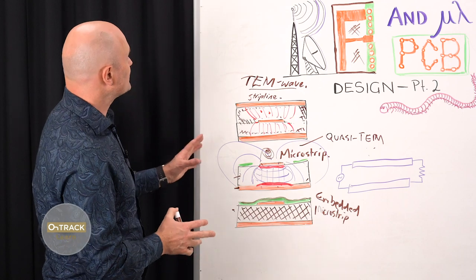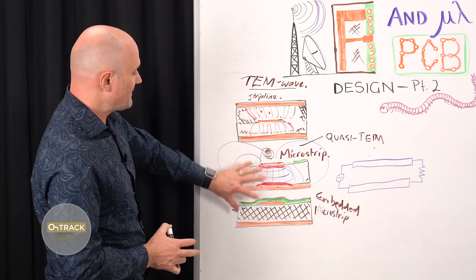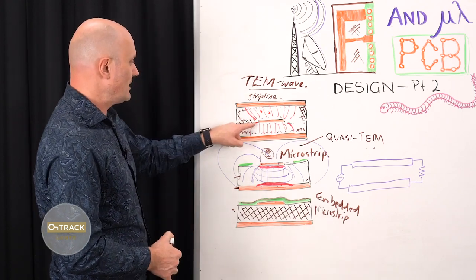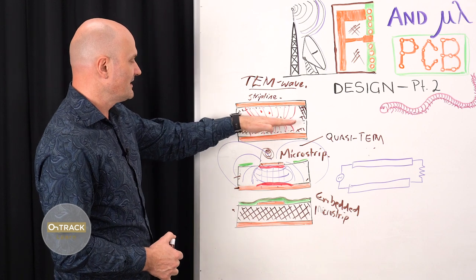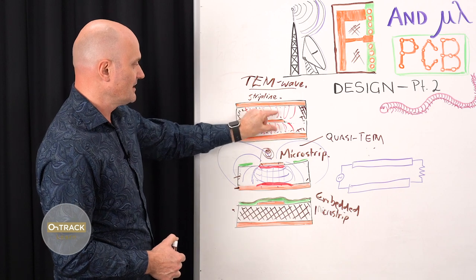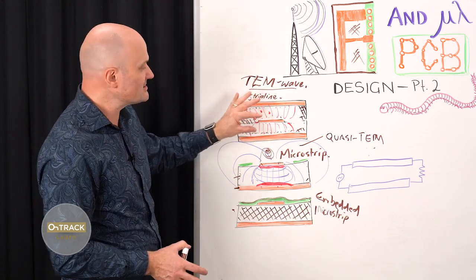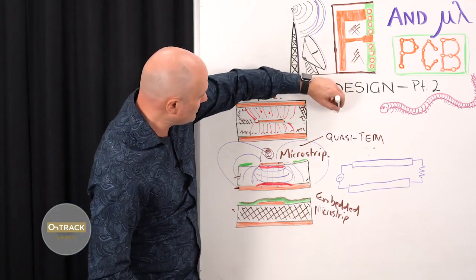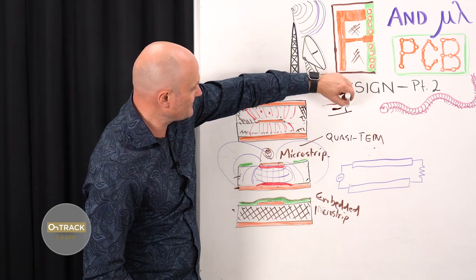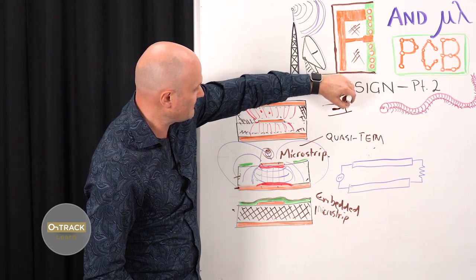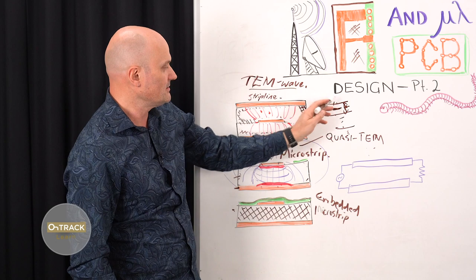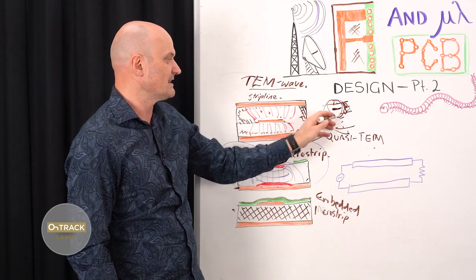Okay, so not to get too far ahead of myself, but these are the fundamental types of transmission line you'll be dealing with in a printed circuit board. And if you're wondering how to get an exact strip line, which has the same distance on one side as the other, typically this is part of a multi-layer stack where your PCB stack-up will have strip line, plane, plane, and you'll have the same distance of dielectric above and below the strip line, and then you'll have some other layers and planes, and you build it up as part of a multi-layer PCB stack.